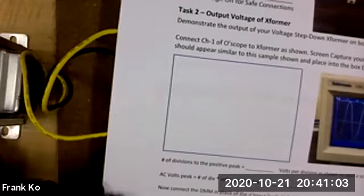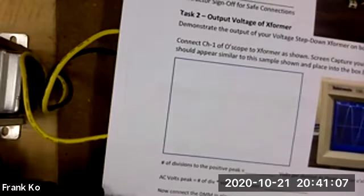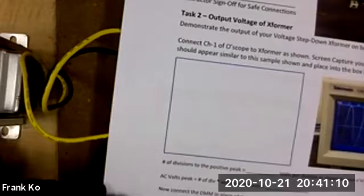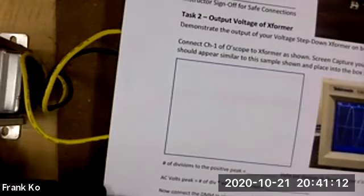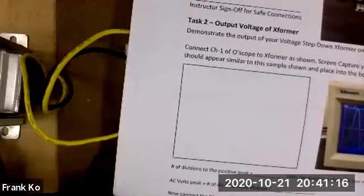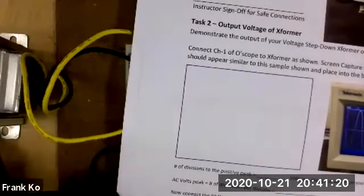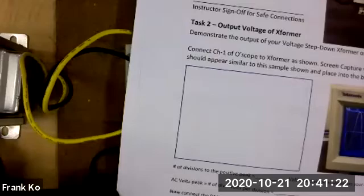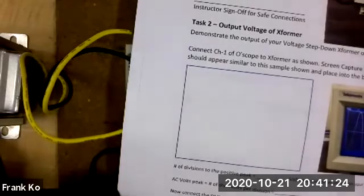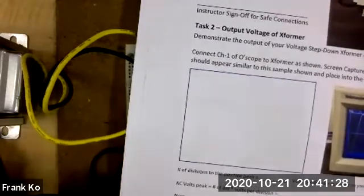And so on yours, you were able to determine about 38 volts peak to peak. Mine was a little higher at 51, 52. So I have 25.6 peak, double that brings me close to 51 volts peak to peak. Okay, so you have an input.